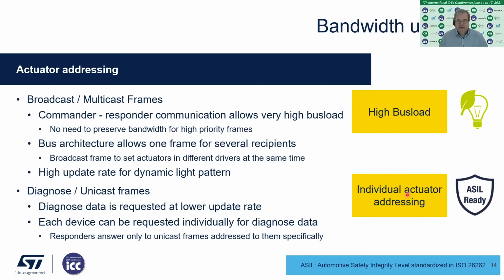And then we also looked at the bandwidth utilization and at the actuator addressing. Therefore, we used 2 kinds of frames. We used broadcast and multicast frames and also diagnosis frames, which we called unicast frames. The idea of the broadcast frames is to make use of the bus topology. Therefore, we can send broadcast frames on the bus to all of the responders that are on the network, for example, setting a PWM number for the brightness of the LEDs.